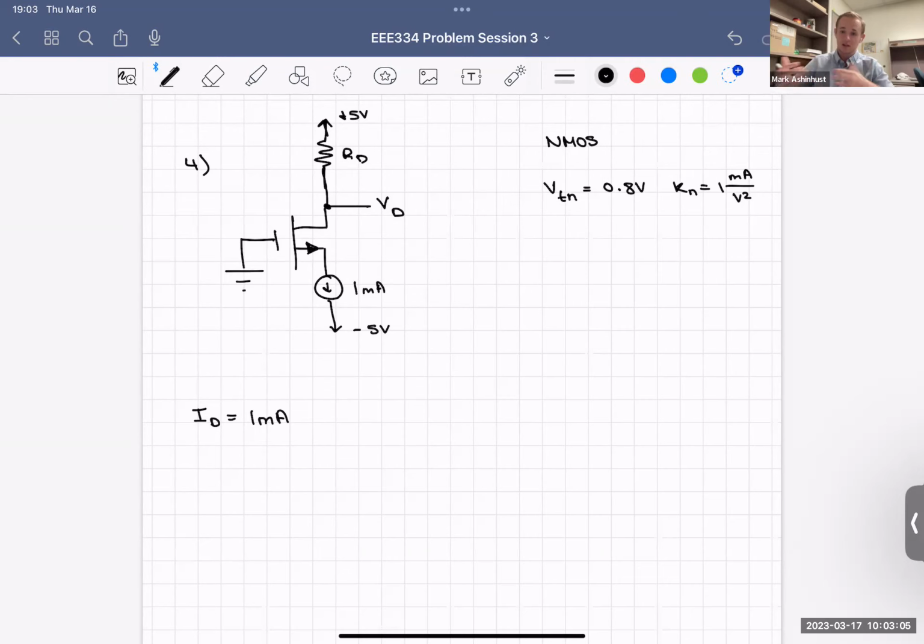So what do we need to know? We want to make sure it's in saturation. So we need to know what VD is, because VDS must be greater than VOV. We know what VG is. And I'll show you a little trick.